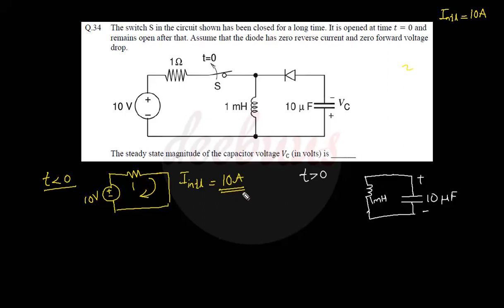Now there is an initial current of 10 ampere. So I have to either mark it as a parallel combination of 10 ampere by S, or a series combination of 10 ampere into the inductor value, so that turns out to be 10 millivolt. Anyway, I am marking it as a parallel combination of a current source, 10 ampere by S. Again, be careful about the direction of the current here. The inductor charging current is in this direction. Similarly, its discharging current must also be in this direction. That's why I marked it as downward. But if it is a capacitor, it is just in the opposite direction.